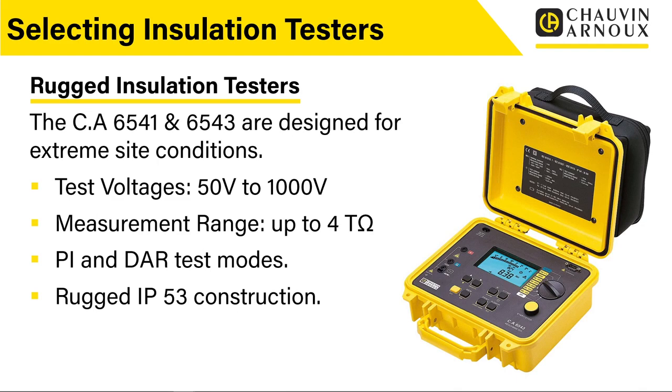And you can see that these will actually measure all the way up to 4 tera ohms. So not mega ohms, not giga ohms, but tera ohms. So obviously a very high and very wide measurement range on here. They've also got the ability to do the PI test and the DAR tests, and actually store the data, download the data, create graphs, all sorts of things within these products.